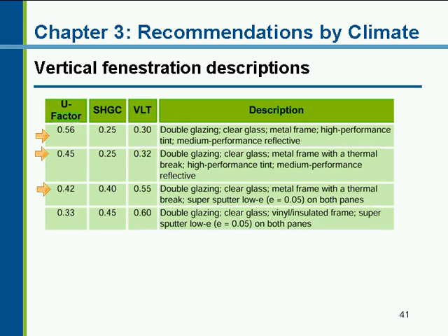And we've got projects in Seattle where people are putting 2 low-e coatings on this double glazing. So they've got one which is the sputter coat which faces the inside of the air gap, and then they've got the hard coat, the pyrolytic, which is actually on the inside surface facing where the occupants are, so that you can actually wash that, and people can touch that window and it doesn't degrade.